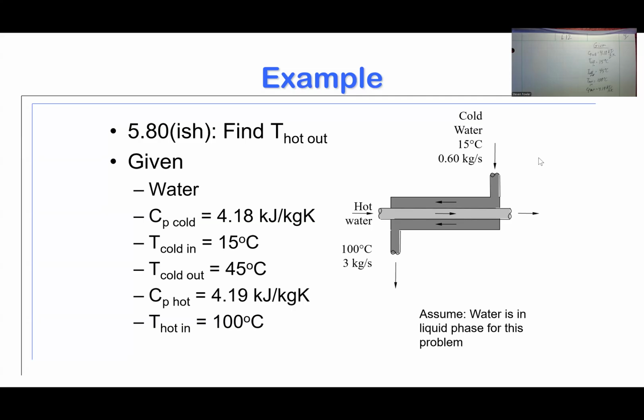So this problem, you'll find one like it in the Chamberlain-Bowles text in the 580s. I'm going to read it to you so you kind of get a feel for what it says. At least the version in the 10th edition I found says cold water with a specific heat of 4.18 kilojoules per kilogram Kelvin, leading to a shower, enters a thin-walled double pipe counterflow heat exchanger.